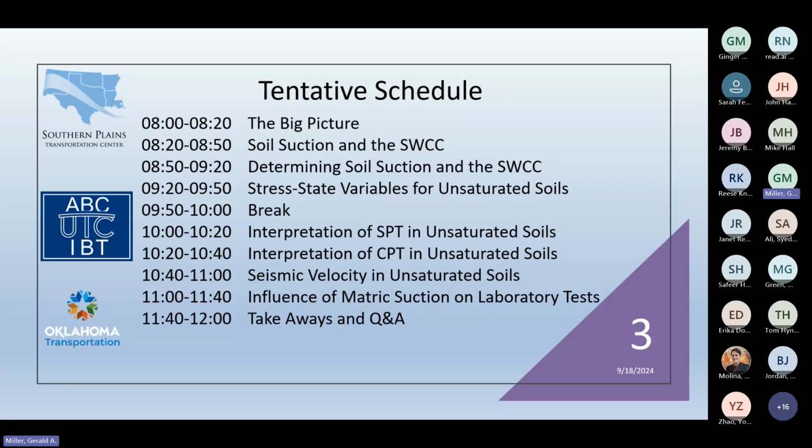Same for the CPT. And then I'll talk about something, I'm not sure how many of you folks are using seismic velocity measurements, but the seismic cone penetrometer is a very useful tool for determining seismic velocities. And those can be used, for example, looking at seismic site class or for doing ground response analysis. So it's a very useful tool.